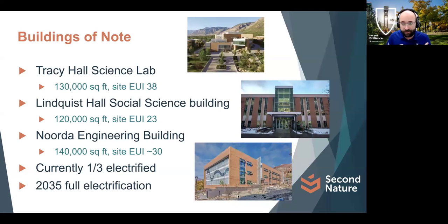But the other idea I'll throw out to the group here is the idea of a hybrid system. So we do have backup heating and cooling for the campus loop. We have some condensing boilers that run during the winter if the ground source fields can't keep the loop warm enough. And then I have cooling towers if I ever need to shed some extra heat. So currently, at our current pace, we will fully electrify the campus by 2035.